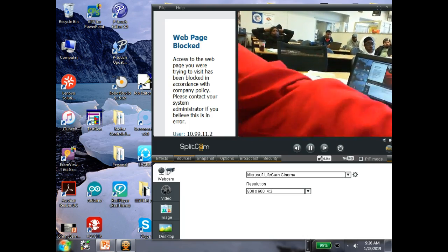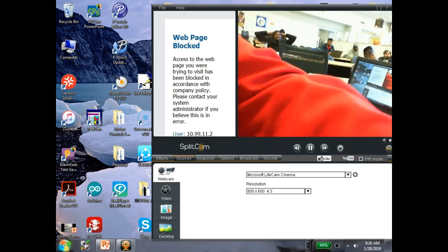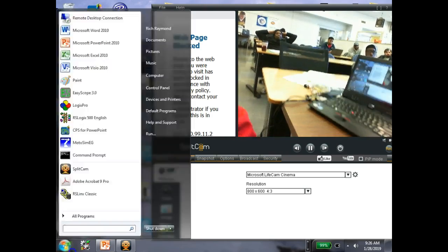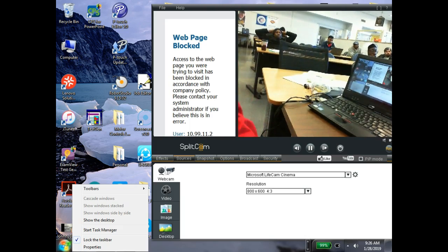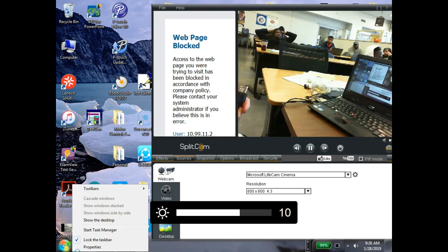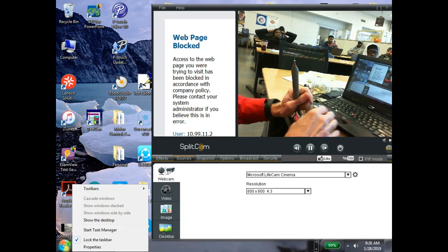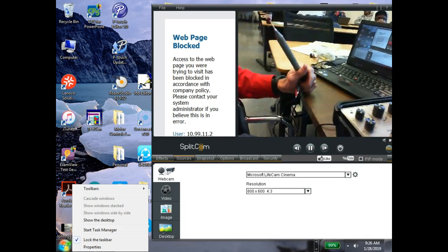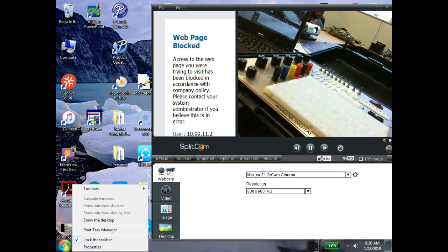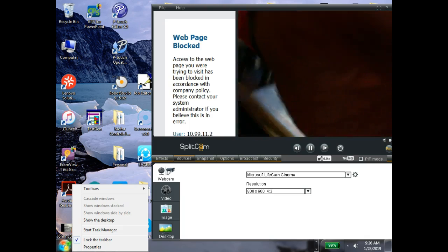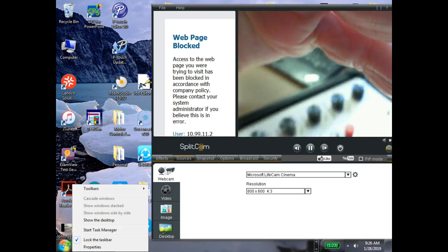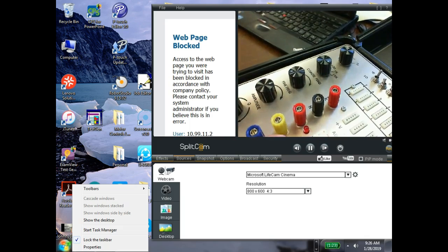So there should be a switch on here that switches you between TTL and CMOS, right? Y'all see it on there? Yeah. And this basically establishes what this thing sees as a 1 and a 0. So what we have is we have fixed power supplies on our trainer. So these are the ones we're going to use.